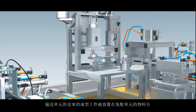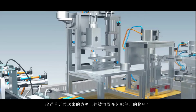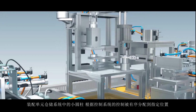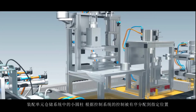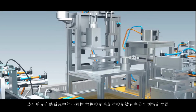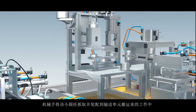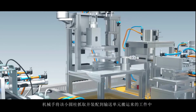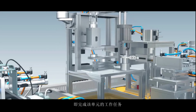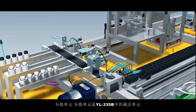The finished workpiece delivered by the conveying unit is placed in the material table of the assembly unit. The small cylinder in the assembly unit storage system is assigned to the designated position according to the control system. The mechanical hand picks up the smaller cylinder and assembles it into the workpiece carried by the transport unit. That completes the task of the unit. The sorting unit is the last unit in the YL-335B.